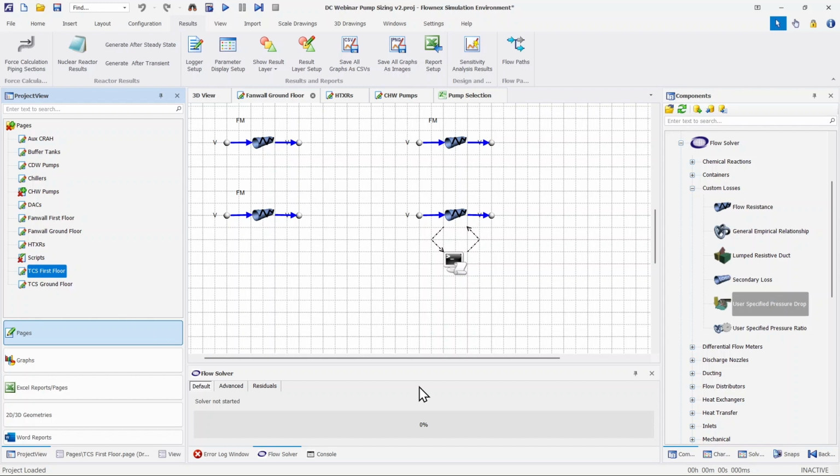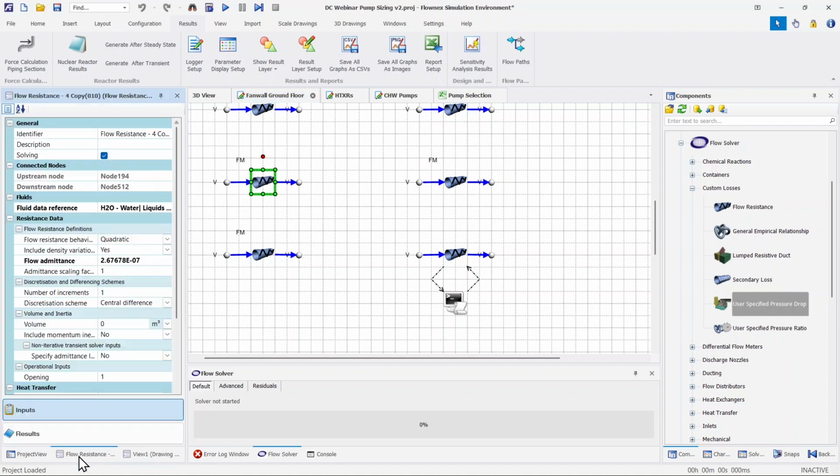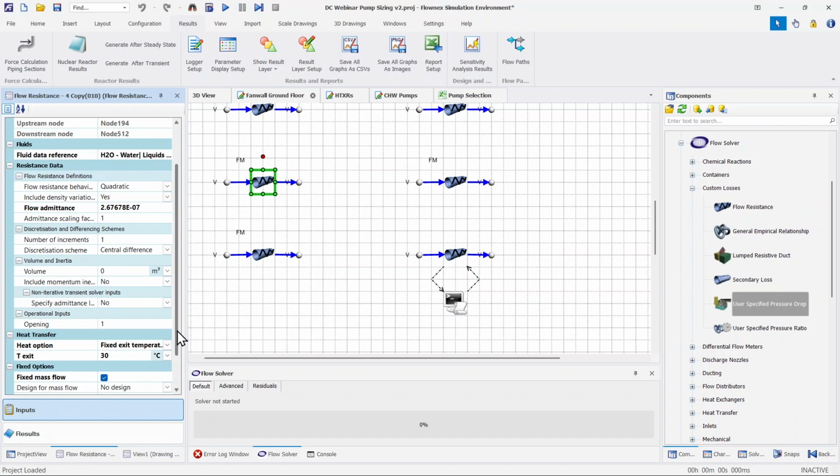For the hydraulic study, we usually use simplified mechanical cooling equipment that is only representative of the pressure loss or pressure rise of the component. When we move to the thermal ride-through studies, these components will be replaced by more detailed characterized models that accurately simulate the thermal and hydraulic transient behavior of the mechanical equipment. Starting with the imported piping model, losses are added for the various piping elements, such as tees, strainers, valves, etc.